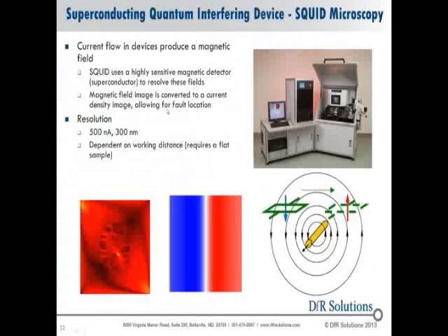Okay, finally the funny sounding thing, SQUID. This is a new technology where it's kind of like the magnetic imaging that is used in hospitals these days. It puts out magnetic fields in order to read the weak magnetic field being produced by current running through various circuits or traces on your circuit board or your components.